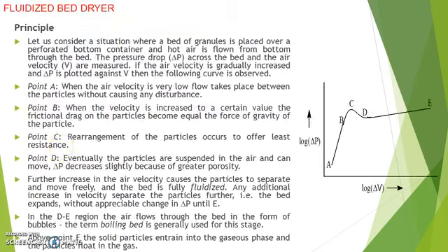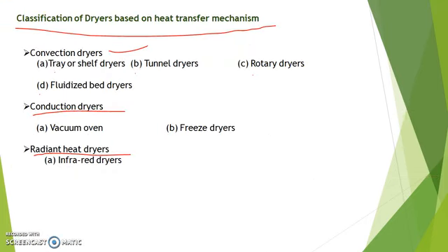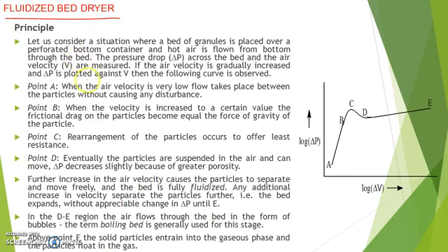So, in the coming slides, we will discuss the fluidized bed dryer. The heat transfer mechanism in this dryer is convection. At first we will see the principle of fluidized bed dryer, on what principle it works. Let us consider a situation where a bed of granules is placed over a perforated bottom container and hot air is flown from the bottom through the bed.